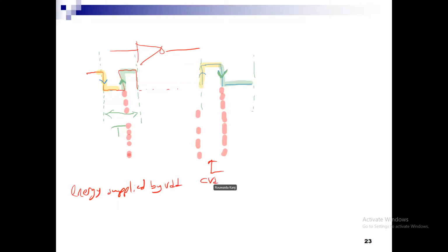Great. We saw now in this first one cycle of the input switching, in the first half cycle, when the input went down to low, up till here, and the output is charged, the amount of energy supplied by VDD was CVDD squared, the amount of energy lost in the circuit was half CVDD squared, and the amount of energy that was stored in the capacitor was half CVDD squared.